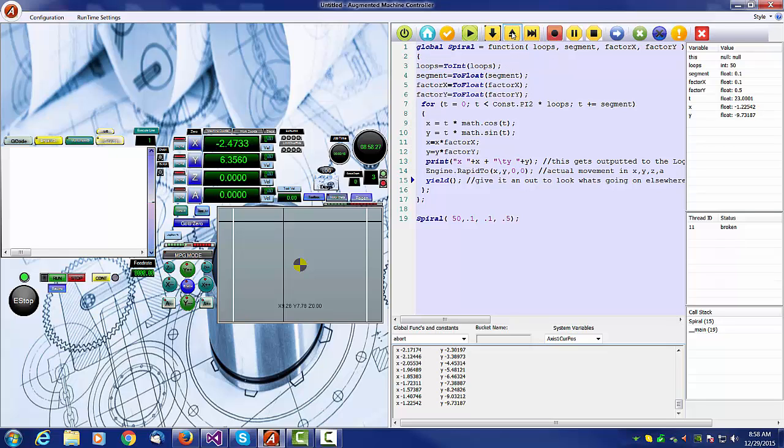You can also step over lines, because you'll notice when I single step, sometimes it can stay on one line for 2 or 3 presses. This is because what looks like one line to you could be 4 assembled lines. And when you push step or step into, you're actually stepping through one machine code line of it, if you will. So it could take 4 presses. But if we use this line down here, step over, it typically takes 1 press per line, because no matter how many lines it translates to, it does them all at once and steps to the next line. So sometimes this is the better line to use when you're stepping through. And you can see our X and Y values are changing as I step through.